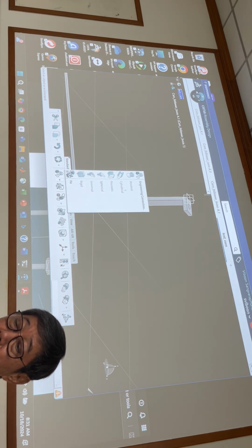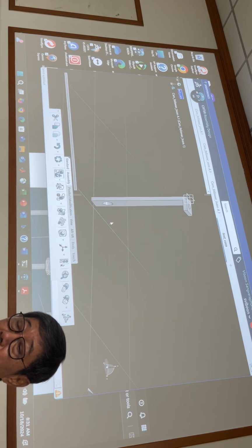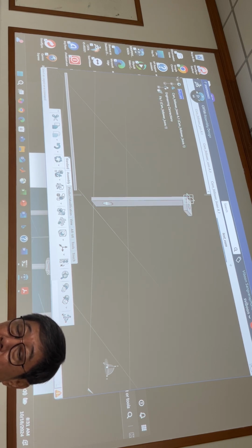We just go to engineering connection and you have the fix command here. Fix, and they're asking which product, which part. I said this one. See, as usual, you have fixed this one. Fix cam follower base. Okay, you have this one. If you want an update, you can update this one. You see.